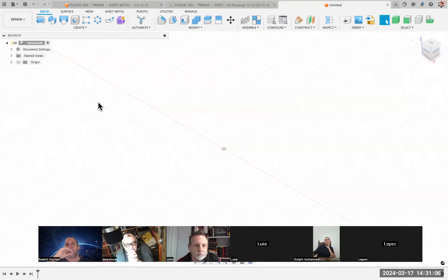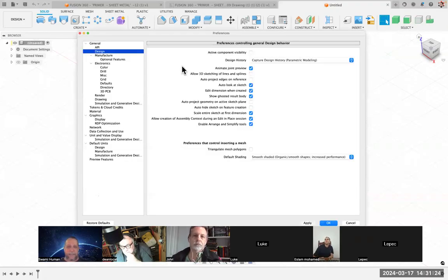So we are going to, by the way, preferences. Everybody has different preferences. Let's try and cut this off at the pass. Go up into your preferences in the top right where you see your initials or your avatar. And that's where we get to our preferences. And let us come up in the left where we have general. We're going to go into the design area of our preferences. And I want us to turn off in the center, auto hide sketch on feature creation right there.